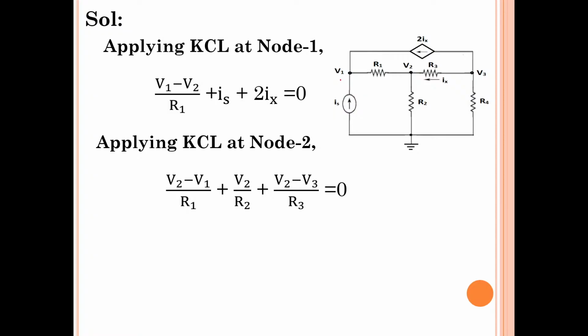It doesn't matter actually, it's your wish. You can write any direction, as I have already told you. You can assume all currents are entering or all currents are leaving. If you assume the current direction is opposite, you will get a negative value. That's it. Magnitude will not change. So here I have assumed two currents entering and one current leaving, and I have added all the currents